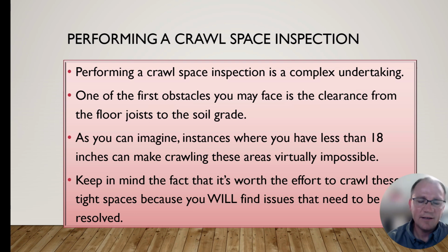I've even had instances where we had to dig our way through a crawl space, move soil and different things. But that's where you're going to find the major problems, especially as we're going to talk later about moisture issues. The closer the floor joists are to the soil, the more problems there can be. So I do understand if it's less than 18 inches, especially, it can be really tough to crawl. But you really want to get underneath there. It's going to be good for your business, good for the customer, and everybody's going to win.